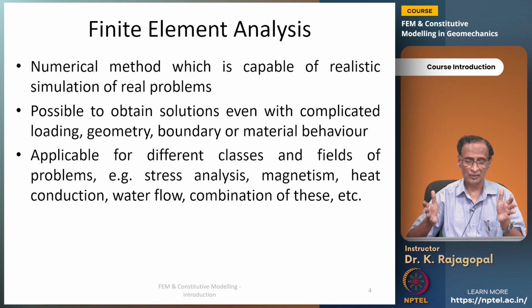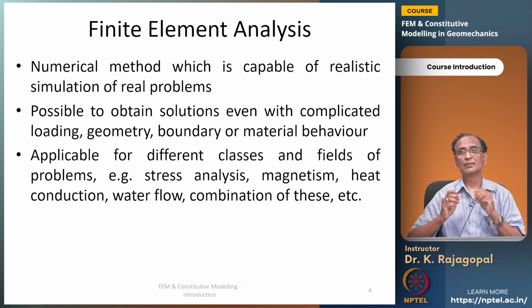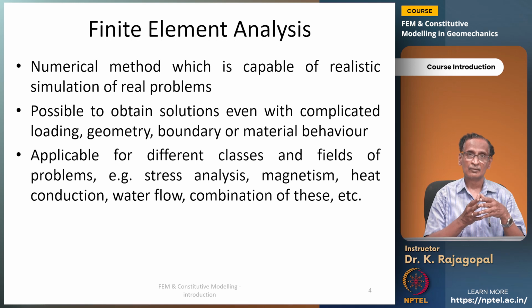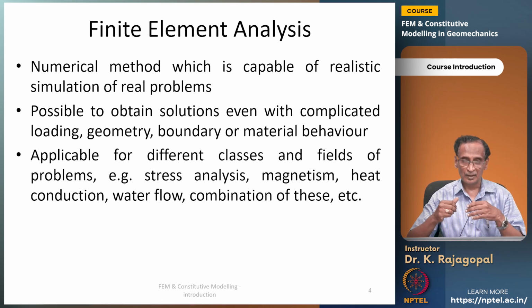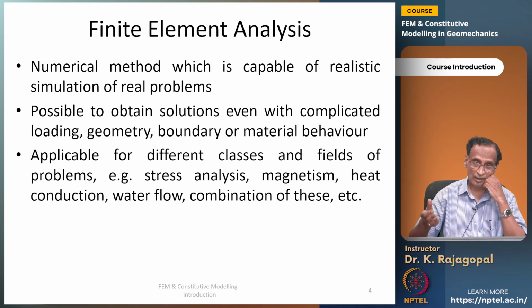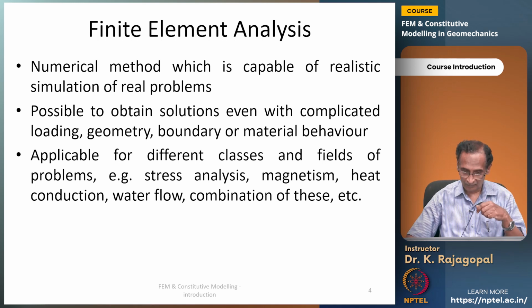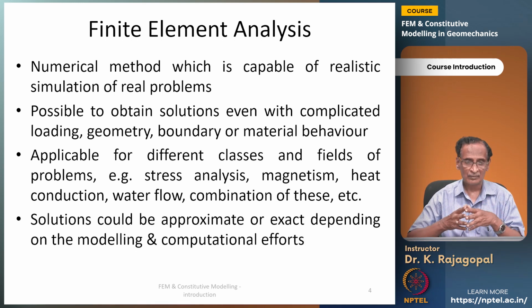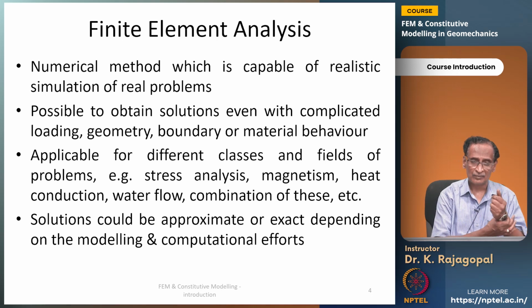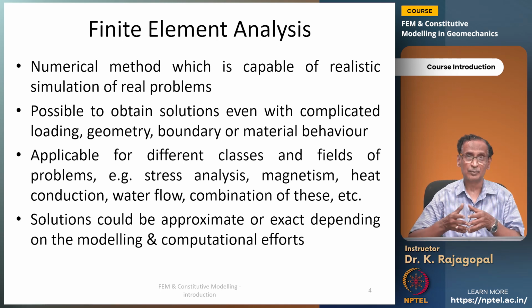Like for example, in our geotechnical problems, we are going to combine the stress analysis with the water. So we will have both the stresses in the soil and also the pore pressures, and then we will have the deformations and the pore pressures and so on, and it comes naturally. Our solutions could be either approximate or exact depending on the efforts that you take in modeling and also the computation.